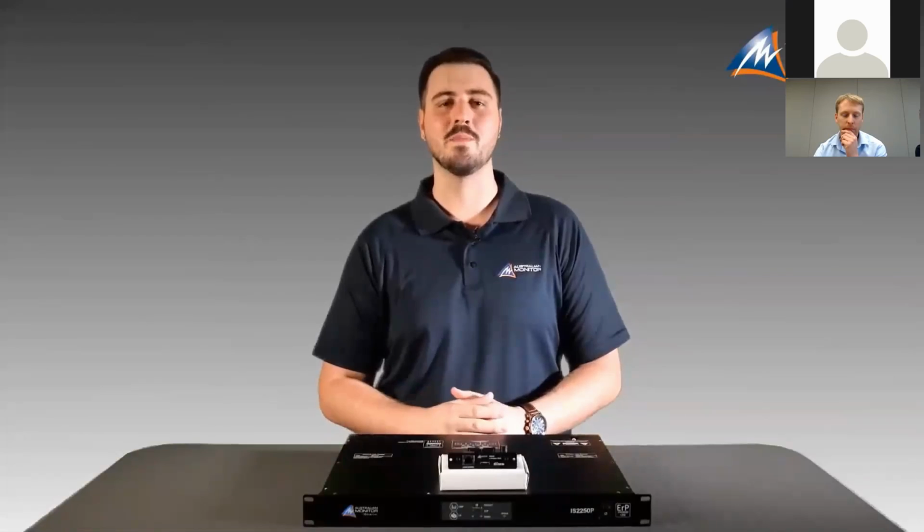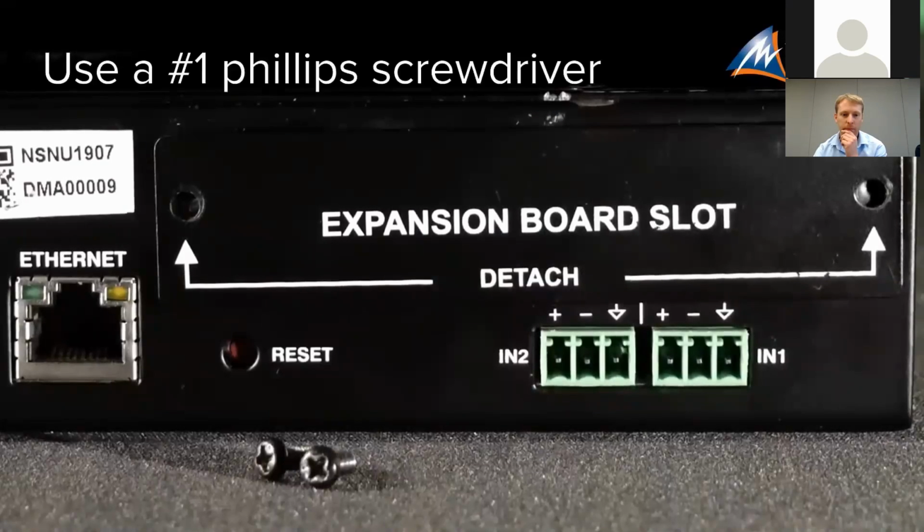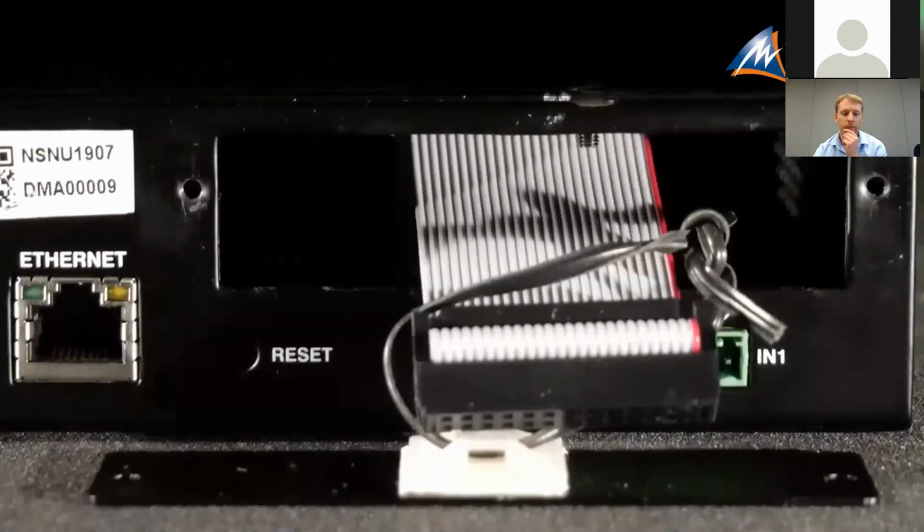Today we'll be showing you how to connect your DM 4x4 Dante module into your Australian Monitor ISP series amp. Firstly, ensure the amplifier is turned off and then remove the expansion board cover located in the rear of the amp. Once the cover is removed, you will notice a cable restraint connected to the ribbon cable. This can be removed and discarded.